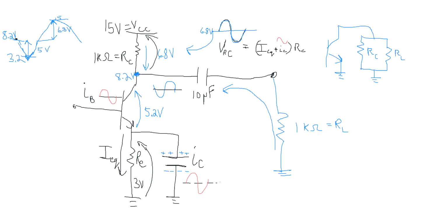We've just gone down only to 2.5 volts. We've squeezed the bottom of this waveform, instead of going all the way down to 5, we've gone down to 2.5. Now, what about the other side when the base current drops? So in the first scenario, I dropped 6.8 milliamps. Basically, I cut off that whole ICQ current, 6.8 milliamps. Now, we're going to see what happens if you drop that same 6.8 milliamps.